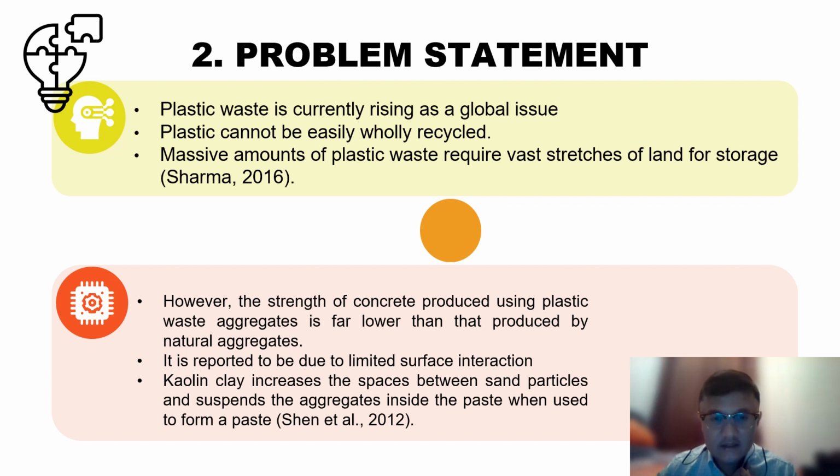Secondly, however, the strength of concrete produced using plastic waste aggregates is far lower than that produced by natural aggregates. It is reported to be due to limited surface interaction. Shen 2012 said kaolin clay increases the spaces between the sand particles and suspends the aggregates inside the paste when used to form a paste.